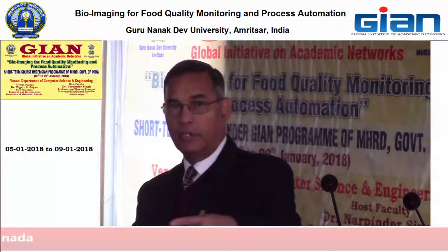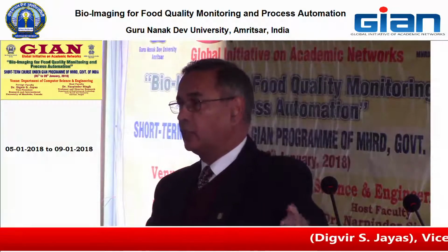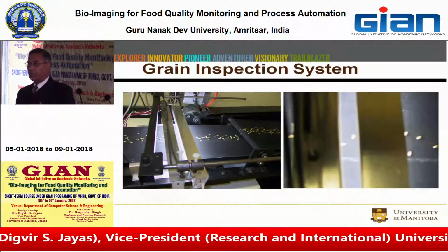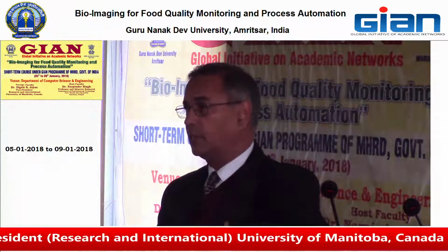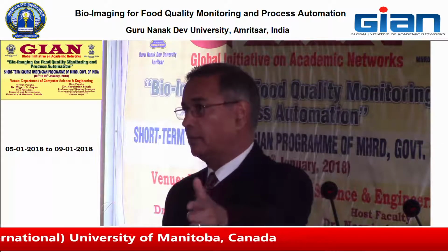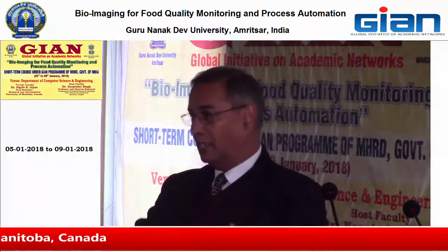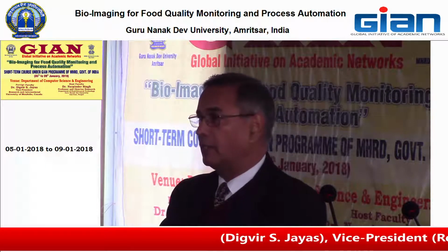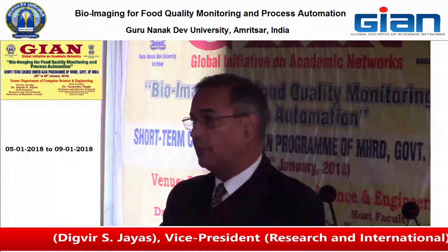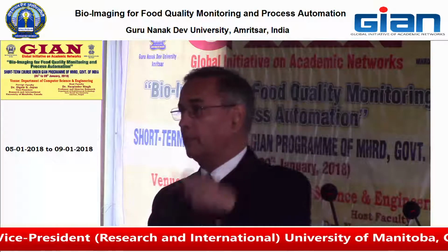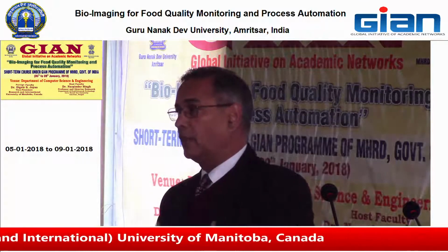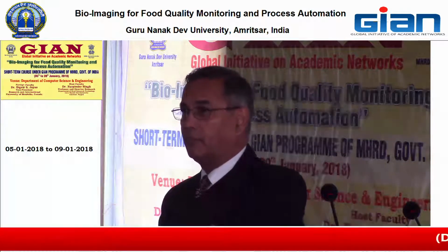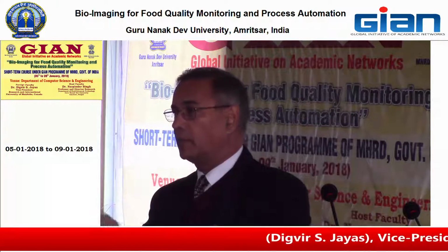In the meantime, the orange may have moved another half a meter. So whatever distance it moves, depending on the time it takes to do the analysis, at that point you can have a piston which would say this is a rotten one, and it just kicks it out. That's how the system would work. So it's a precise calculation. If your algorithm takes longer, then your piston would have to be further away. If your algorithm can make an instant decision, like within a microsecond, then the piston could be just a few centimeters down.